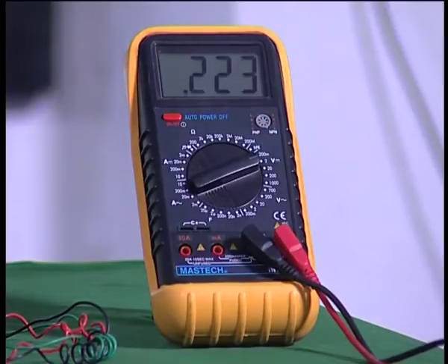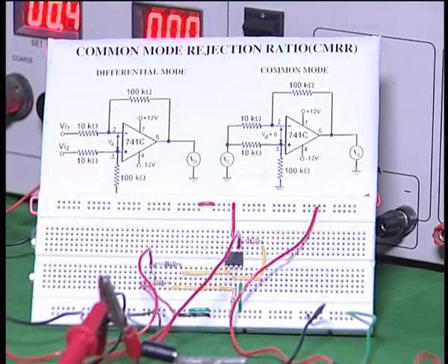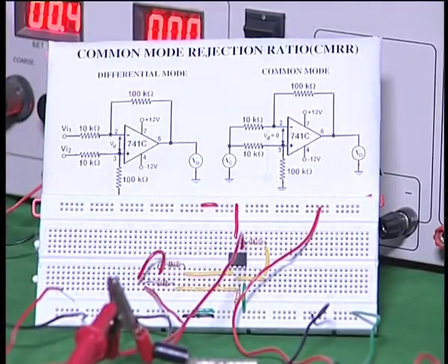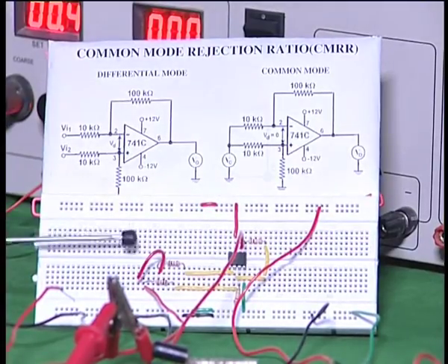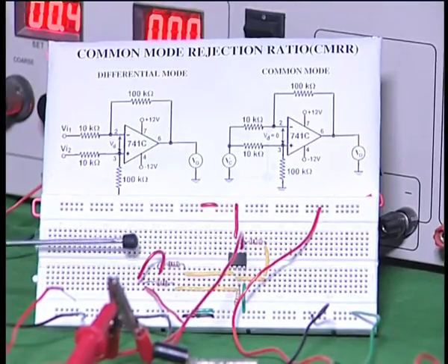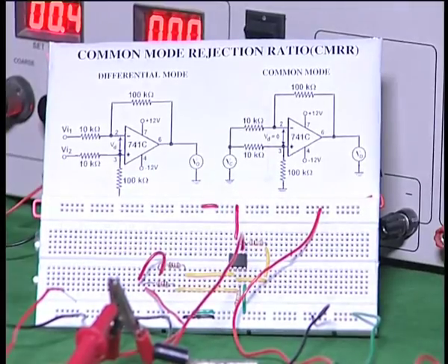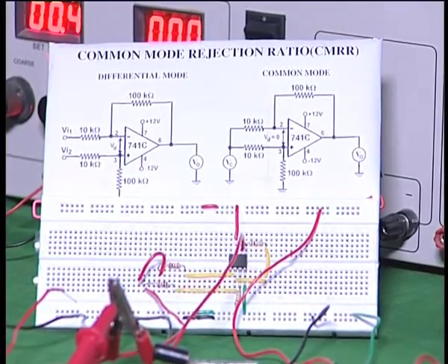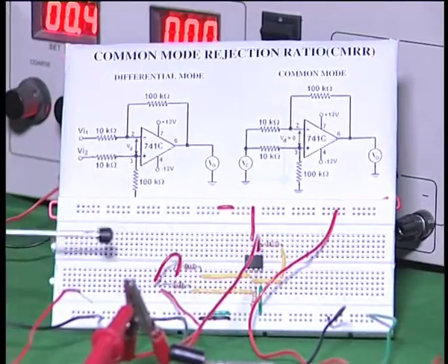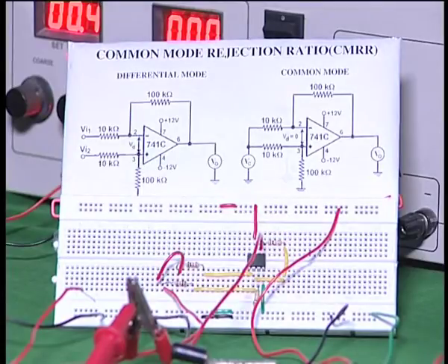Now what I am going to do is remove these two input voltages and connect the two input terminals together and connect one voltage, one of the 0.5 volts, alone. Now you can see there is a red wire which has come into the circuit, which is connecting the two input terminals V1 and V2, and there is only one source connected at the input, and this is already 0.5. I have not changed anything here. Therefore 0.5 volts is given at the input, and what is the output voltage?